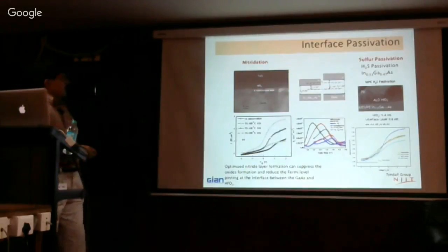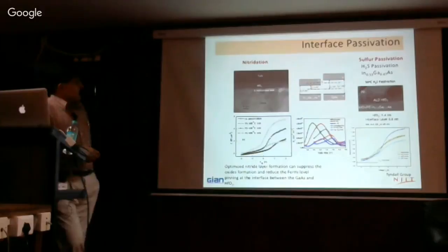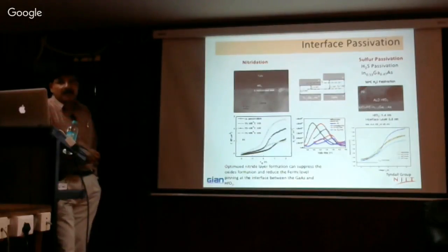So then you can see, if you have gallium arsenide and indium gallium arsenide, you can change the percentage. People are trying different percentages of these indium gallium arsenide samples so that they can adjust this interface and the distribution of defects inside the band gap.